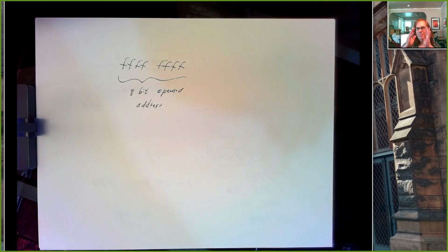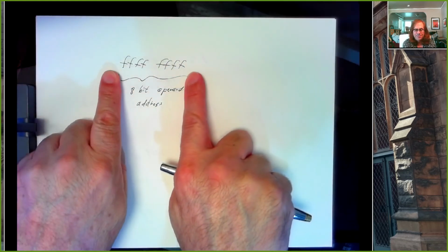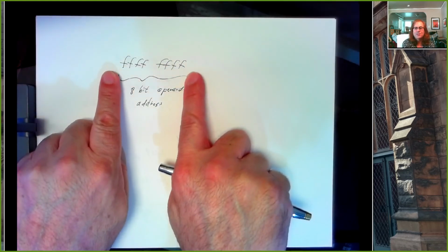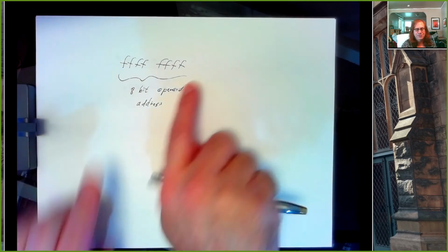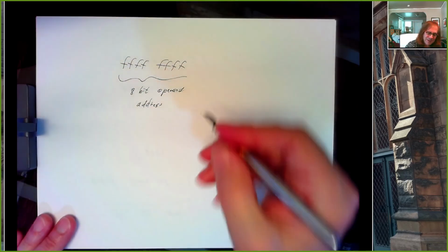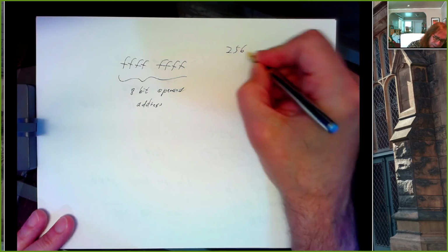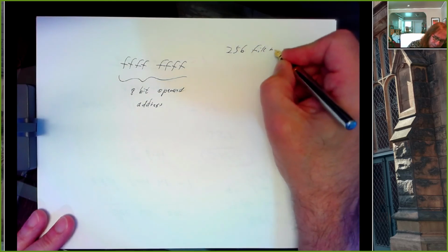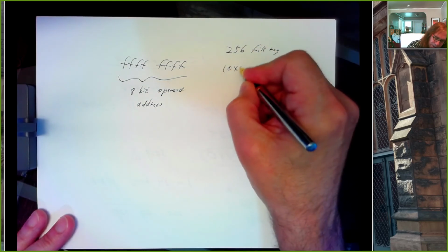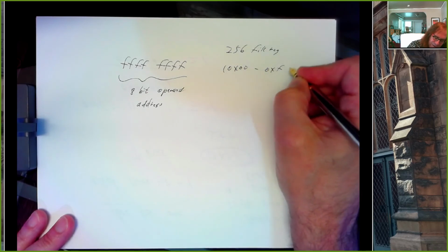if you look at the coding for it, it's a pattern of 6 bits. It's 2 bits for the D and A bit. And then there's 8 bits that specify the address of the operand, right? The location of the file register you want to increment. And since we have 8 bits, we have 256 file registers. And in hex, there's 00 through FF.